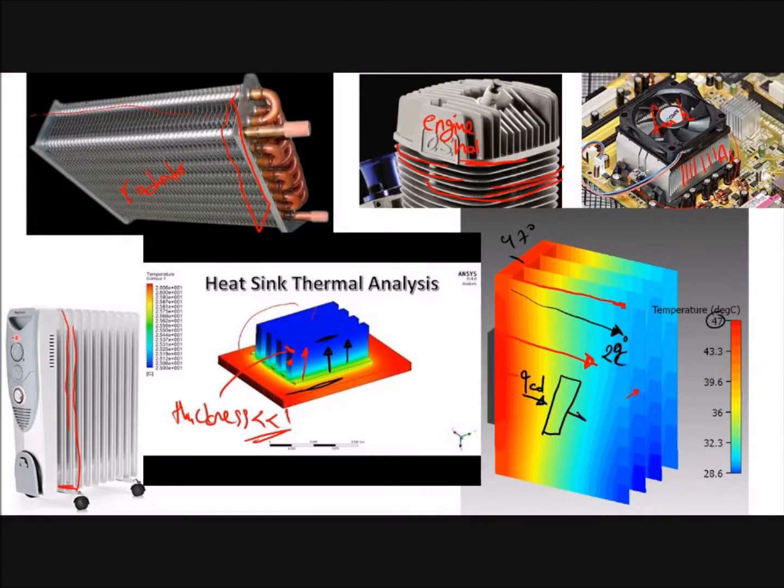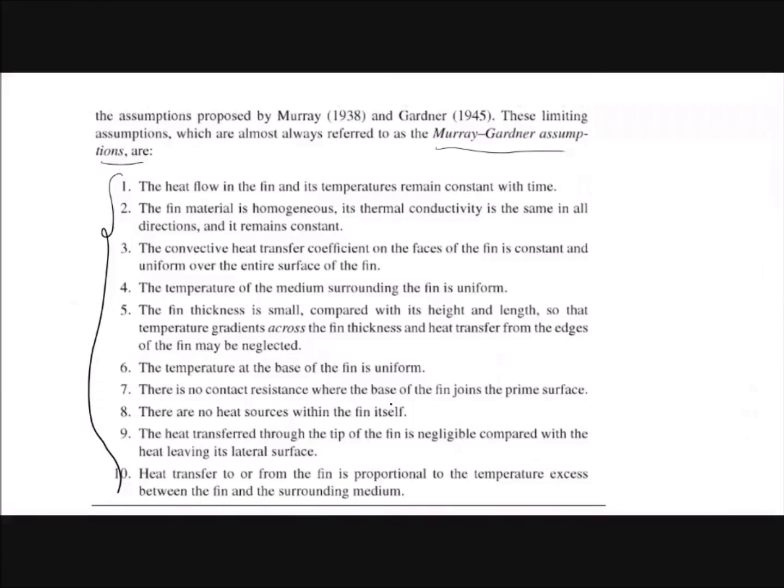You have heat transfer out of the volume by conduction, Qcd. And you have also convection by the environmental air. Steady means whatever comes into that small elemental volume is equal to what leaves that elemental volume. Therefore, it is steady. There are no transient effects happening inside this control volume.